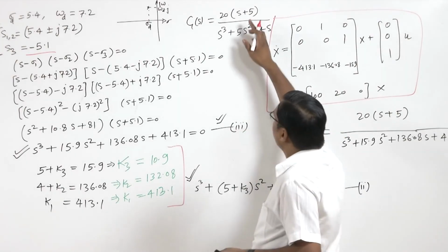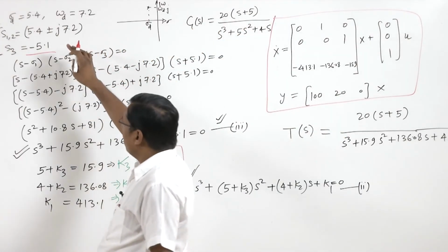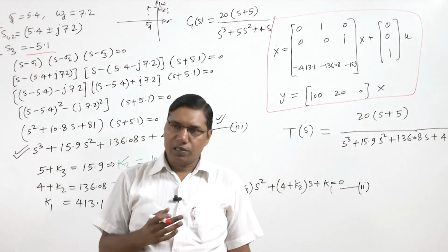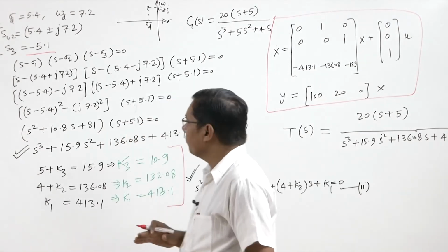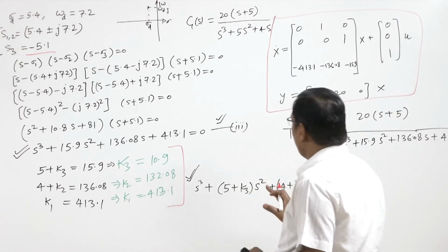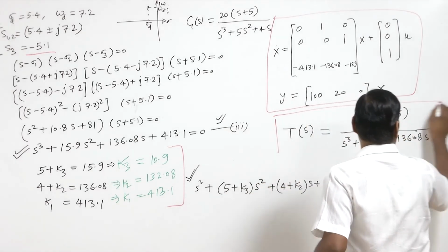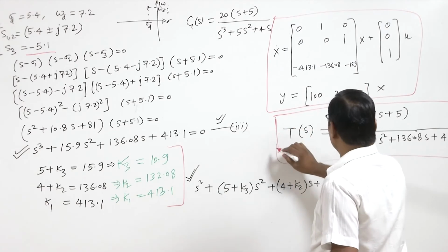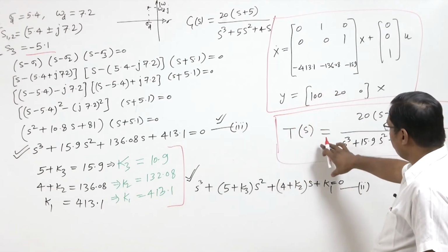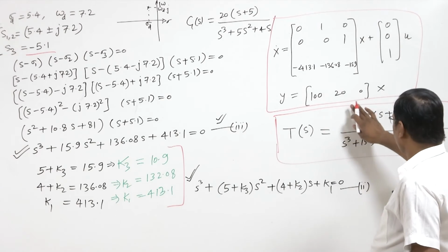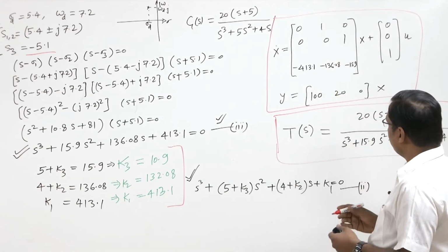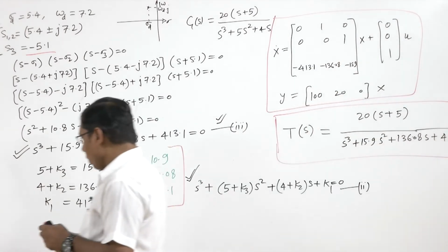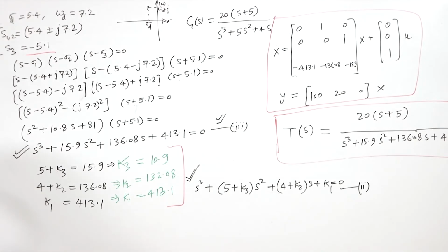Here we applied the pole zero cancellation, but here we could say that the condition that the third pole is very far, so it is not affecting much the dominant pole's response. And this is the transfer function. So the system is the same. We have 2 different representations. One is the transfer function, that is the frequency domain approach, and this is the time domain approach, that is state space. So now we have discussed for these systems how to find this.